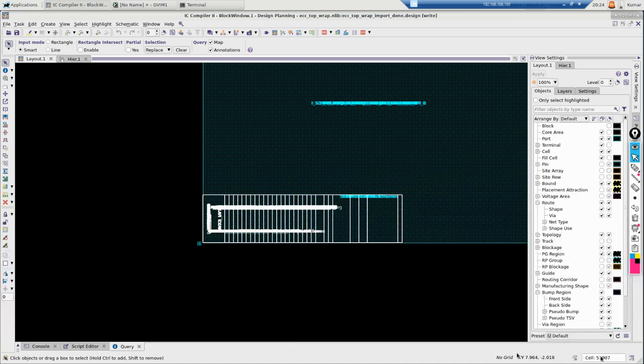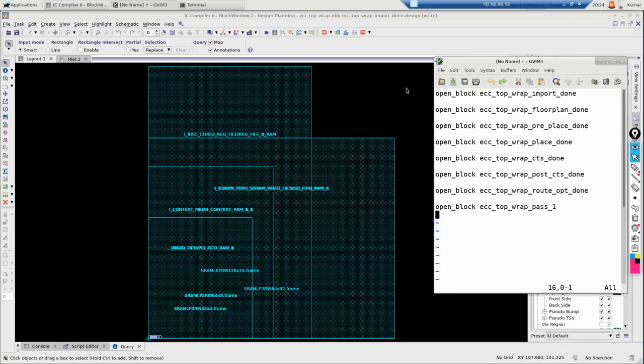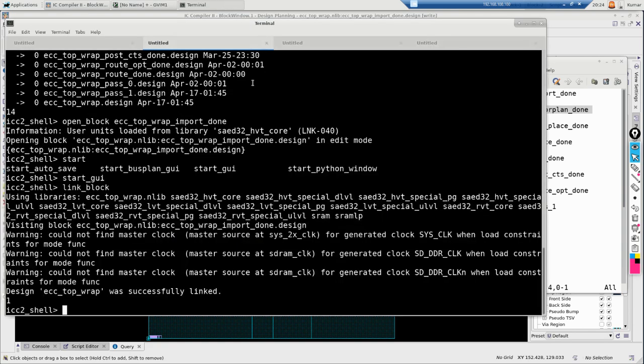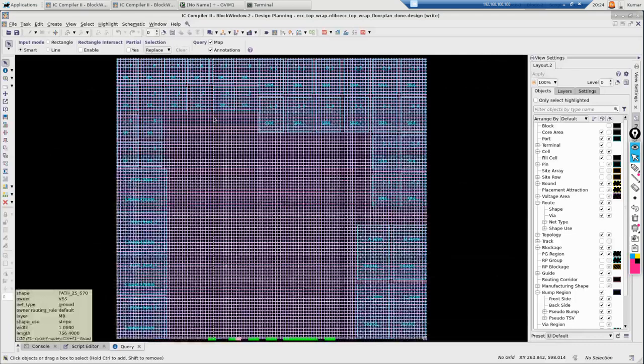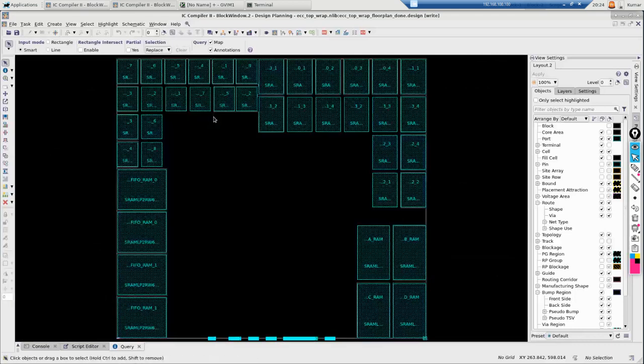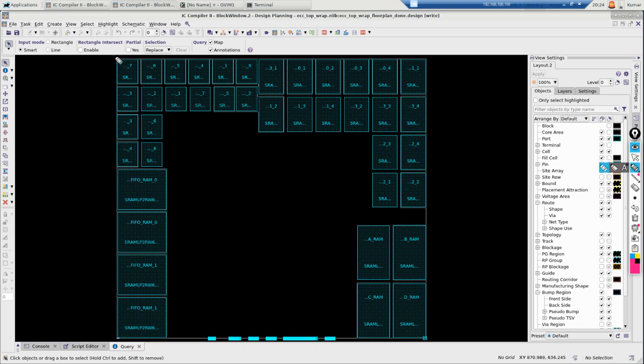Okay, so you have got around 52K cells. All your cells are just sitting at 0 0 without any physical area assigned. Now the next step we discussed is that you need to assign an area, and then you need to place all your macros and everything. Now look at this. So this is the area for your block.